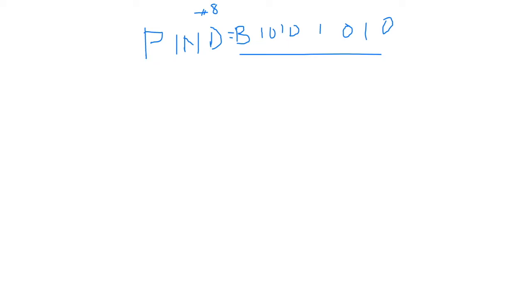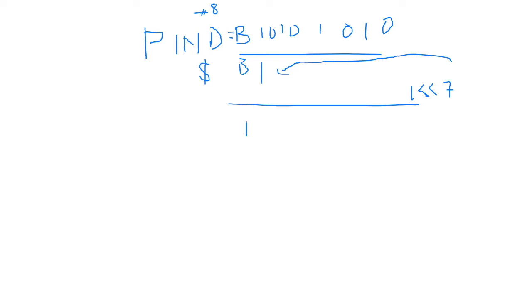And then what we are saying is, if we put an AND, whichever pin we are interested in, we will set that pin to a 1. So let's say at the moment I want to read this pin alone, which is maybe D7. I will just shift a 1 seven times to that position, so it will go all the way to that position, and I can read what is on there. If it's a 1, I get a 1. If it is a 0, I'll get a 0. And all these others, if I AND them with 0, will become 0 anyway. Okay, so that is clear.